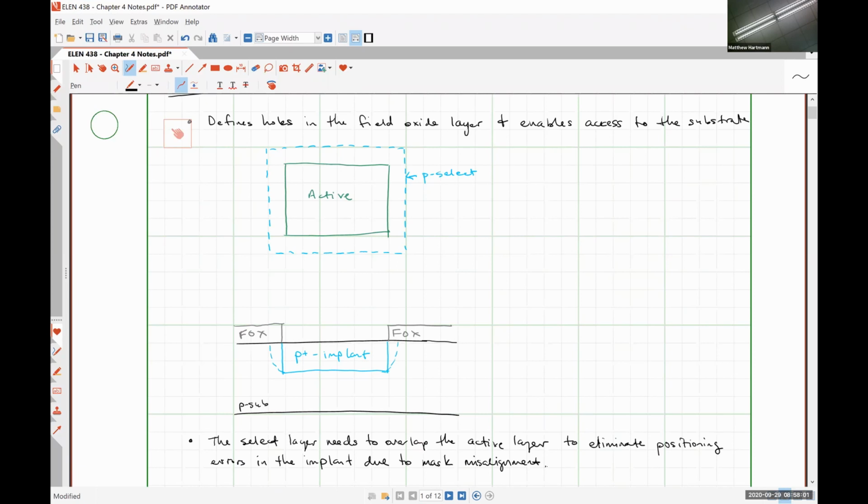And so what that means, like let's say that you were trying to put in the implants for a transistor, right? So you actually shine the ion beam, or not the ion beam, but the dopant beam over an area larger than it needs to be, because if you bury a few excess charge carriers inside this highly insulating field oxide layer, it's not going to turn it to be conductive. But if you were to shine it directly on just the area that you thought you needed, and the masks were misaligned and things like that, you could have regions like